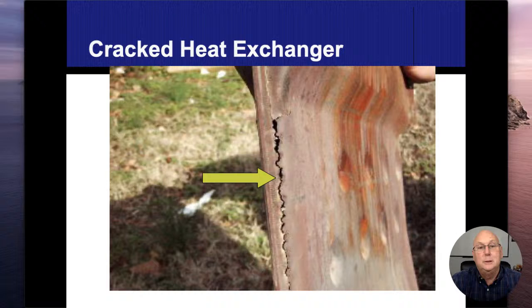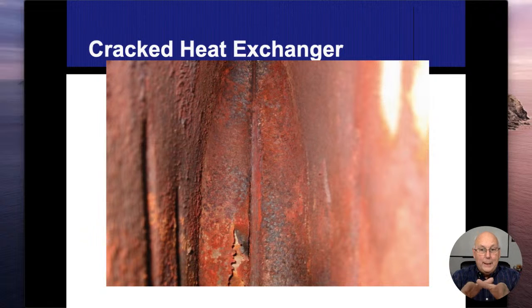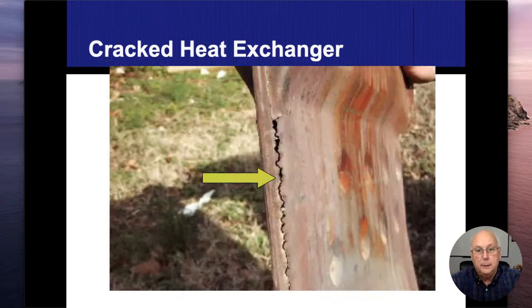Another heat exchanger, the entire back of it was blown off. And that's very common. If you notice when I go back, straight to the rear of the heat exchanger is probably one of the most common places that they crack or break. We saw it on all 3 of these actually. And then right where the burners come in, right up underneath it as it comes back, there's a lot of bends in there and high flame impingement. I shouldn't say impingement, but there's high heat in there. And those are other areas that crack and get damaged quickly.